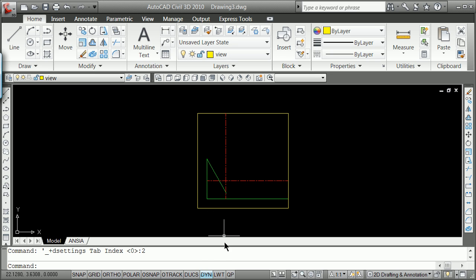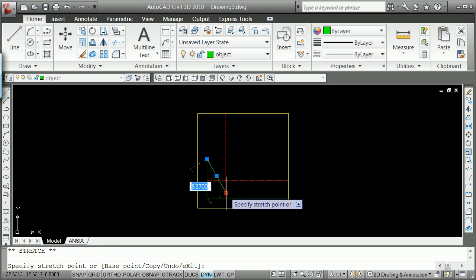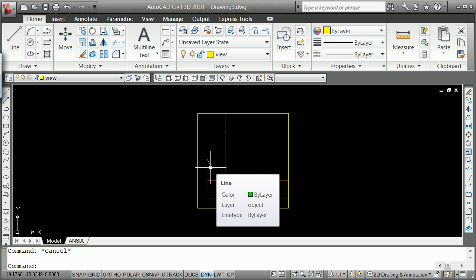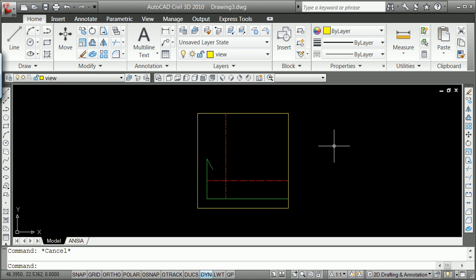I turn on the dynamic now, and I left click on the thing I want to change. I left click on the length I want to change, and I type in, in this case, 2.53. And I hit the escape key there, and my length is changed. Once again, this skill of turning an angle is quite useful, because very often you're interested in the absolute angle between two lines. It's definitely what you're interested in when you're doing a land survey, but there are lots of different things where this comes up. All right, if you're a rough carpenter, this probably comes up.